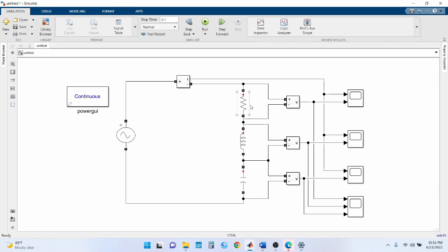And in that, when we compared the voltages and currents of our resistor, inductor, and capacitor, we verified how the current and voltages behave with respect to these elements, such that the voltage and current remain in phase for a resistor, but for an inductor, the voltage actually leads the current, and for the case of a capacitor, the current leads the voltage, right? So we actually verified that experimentally.